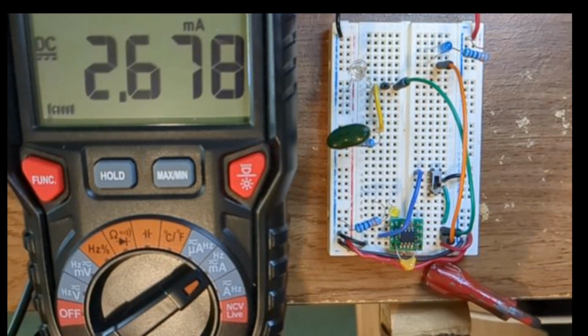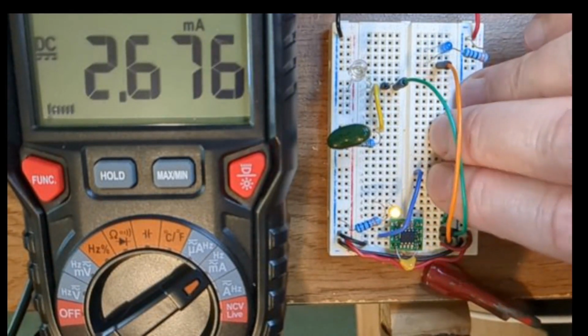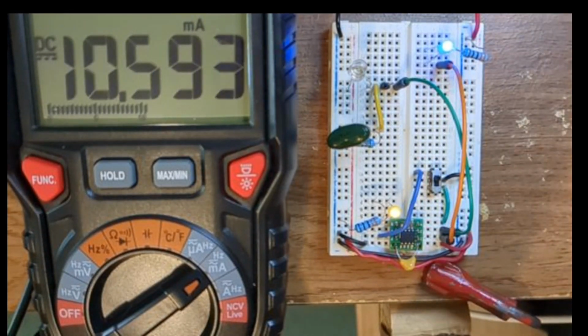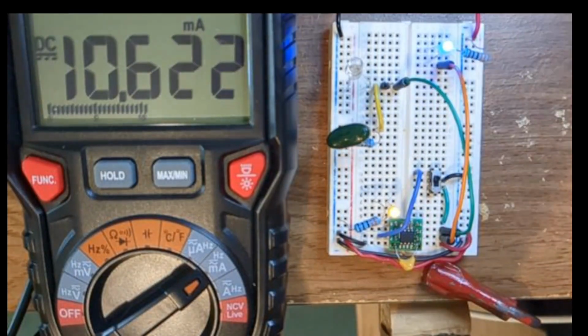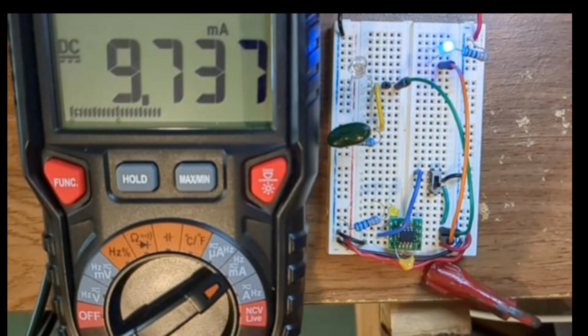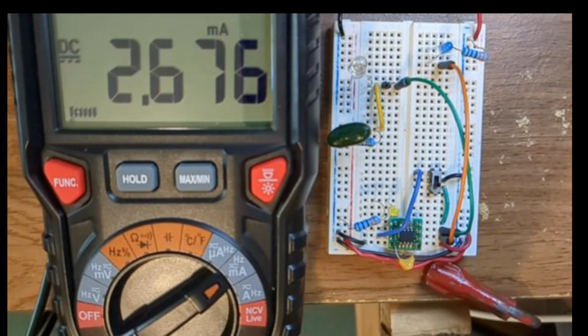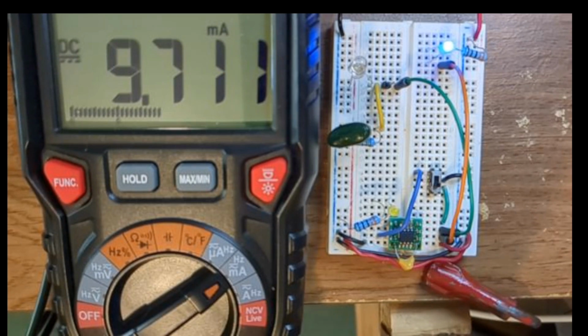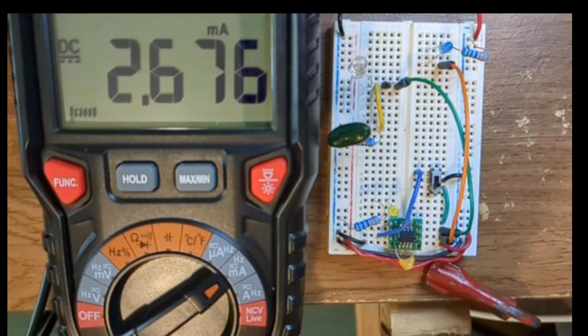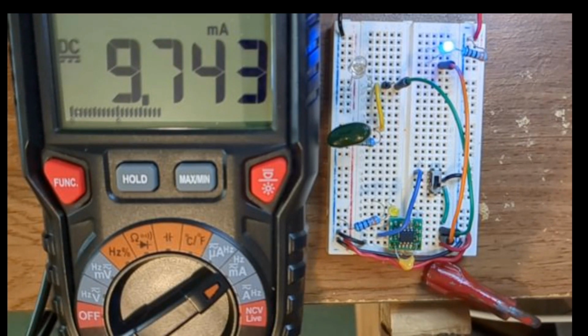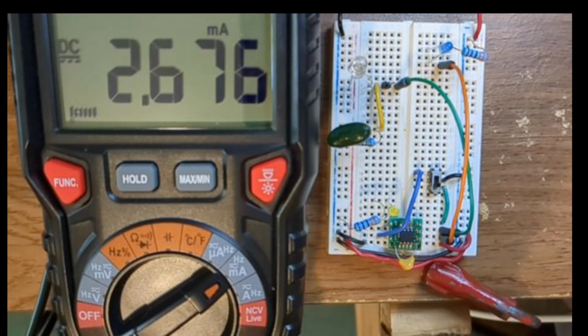There's also a switch that I can use to turn the LED on regardless of the brightness state, so it doesn't matter, it just stays on. What's interesting is that the ATtiny can perform this nightlight function with no software other than software used for initialization. When initialization is complete, the core doesn't have to do anything, and the nightlight function continues. In fact, the core can be put into a low power mode, standby mode, and this function still works.